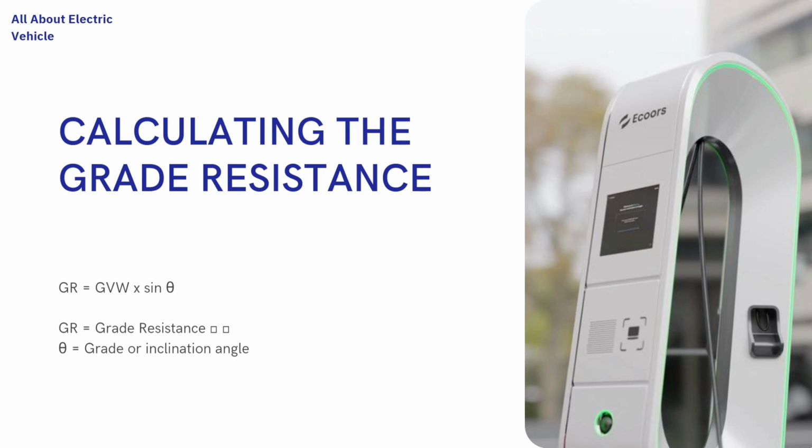The angle of inclination of the road surface, theta, is the angle between the road surface and the horizontal plane. This angle is usually measured in degrees or radians. The formula for calculating the grade resistance is based on the fact that the force of gravity acting on the vehicle is proportional to its weight and the sine of the angle of inclination. The greater the angle of inclination, the greater the force of gravity, and the greater the grade resistance.